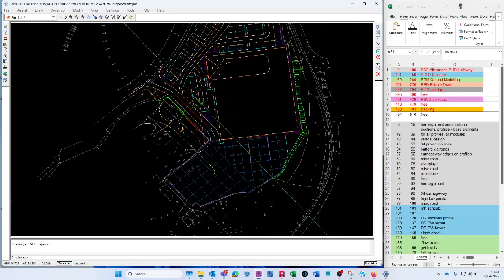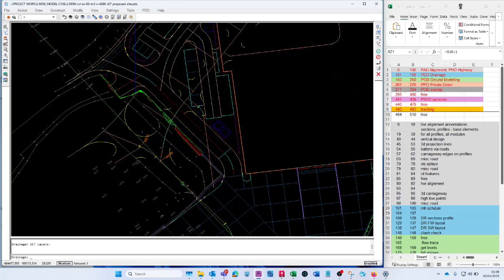You then select your horizontal lines and you go project this road alignment as a 3D surface. So it takes that alignment, takes those graphs, and it creates a massive string line which the road hangs off of.